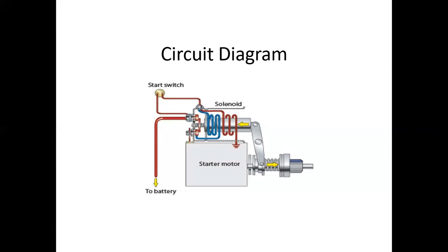Once the starter motor rotates and high power is produced through the rotor, the solenoid automatically moves to the left side. That is the yellow mark in the solenoid, which moves to the left. Automatically the connected rotor then connects to the engine crankshaft. This is the circuit diagram of the solenoid circuit. It is a simple one here, but the circuit is always more complicated in practice.